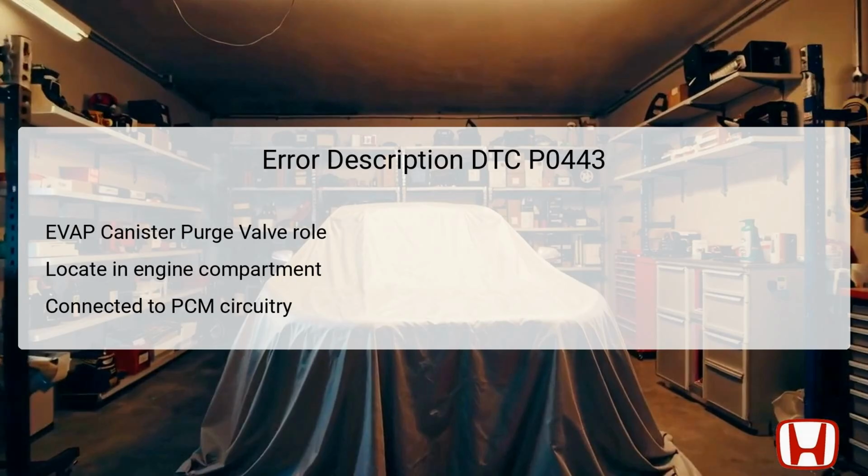compliance with emission standards. If the circuit malfunctions, it can lead to a rise in harmful emissions and may trigger a dashboard warning light, indicating the DTC P0443 should be investigated. Understanding its function is crucial for effective troubleshooting and repair.